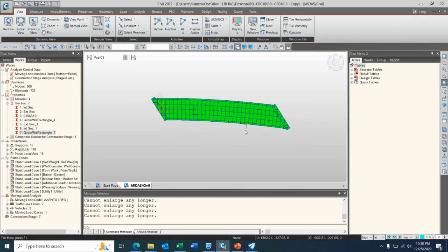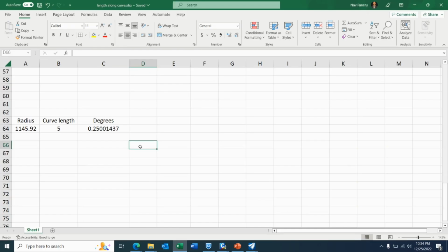This is because of the tighter radius in the inside face, because I'm using constant 5 feet wide cross beams, so it's not gonna be exactly side by side throughout the curve because of the varying radius. So yeah, this is the approach we are going to use for our modeling as well. So now let's take a look at the spreadsheet. I'm using radius of center line of the bridge and calculating the angle corresponding to 5 feet width. Now I will draw a line normal to the curve and rotate that line by this angle throughout the bridge.